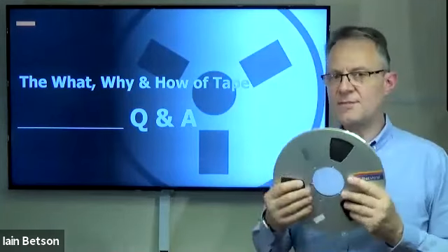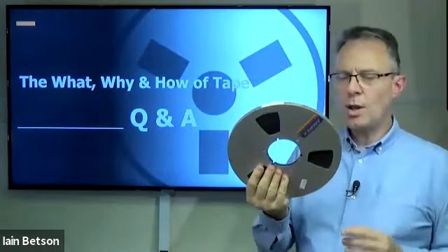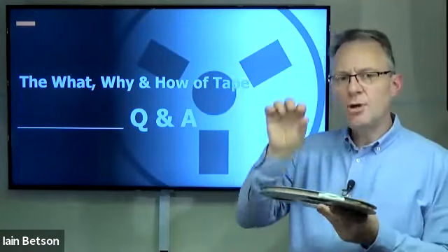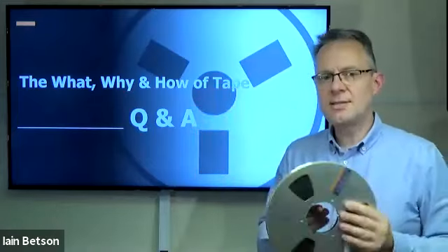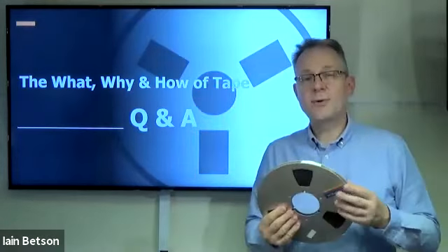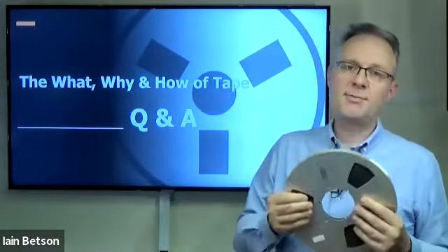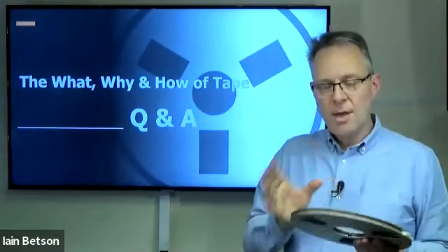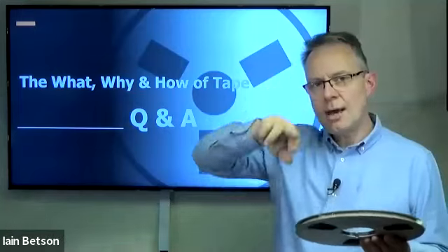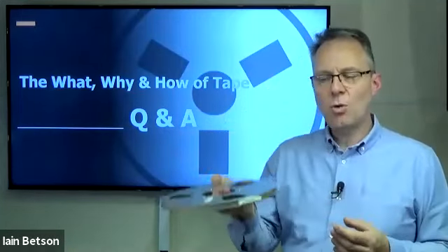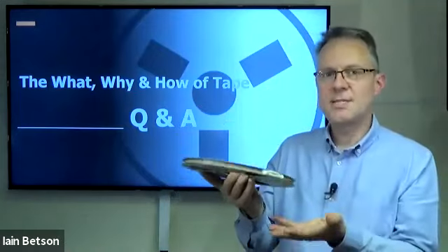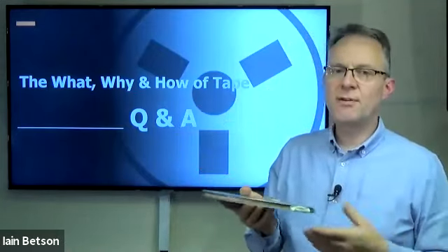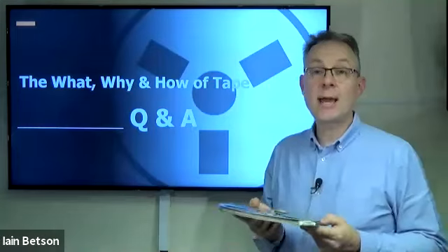Now you might be thinking that's fine if it's a 2-track tape, that's all it is, just 2 tracks, and I don't turn it over, whereas a 4-track tape where you might have 2 tracks in one direction and then you turn it over, physically turn the tape over. You're not going to get over the effects of print through on both sides, because at any one time with a tape that's got an A and a B side on it, if you store it tails out to protect, say, the A side, the B side is effectively tails in, so we'll be suffering from this pre-echo issue.